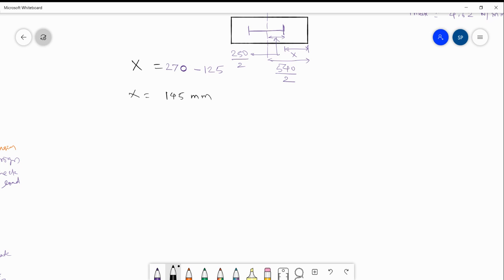So this total base plate, if you consider, over this length the section is critical, and at the junction, at this particular location, is located the critical section. So we have to find out this Vx. Now, the base plate will be subjected to upward soil pressure here.